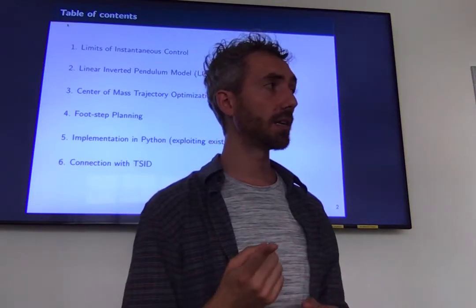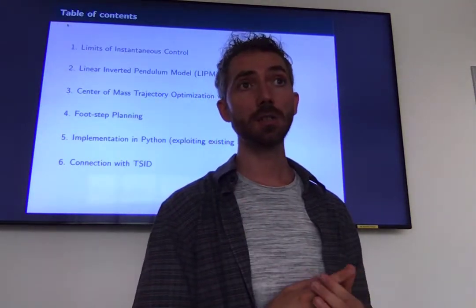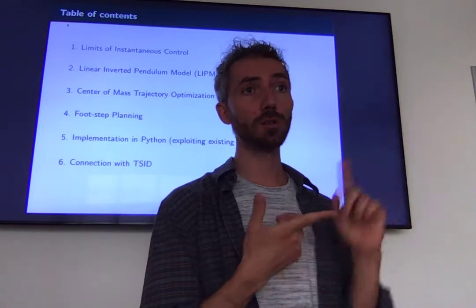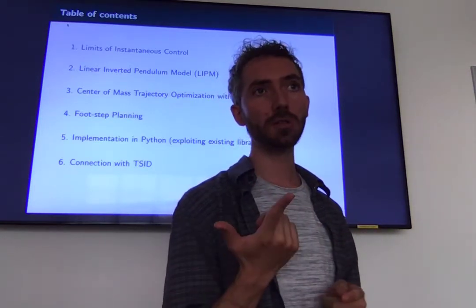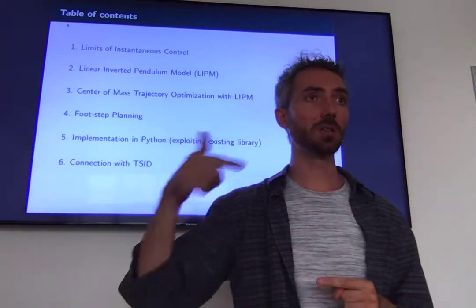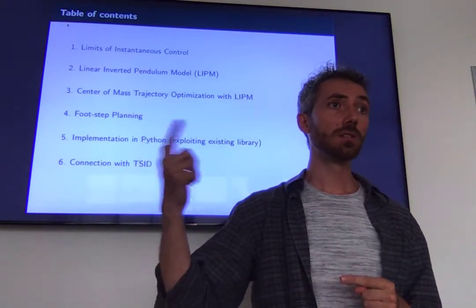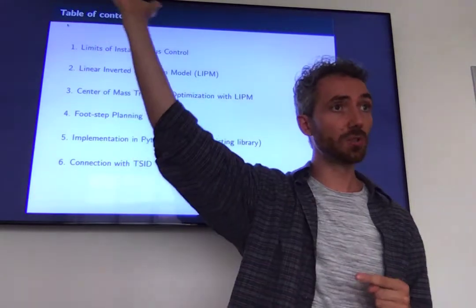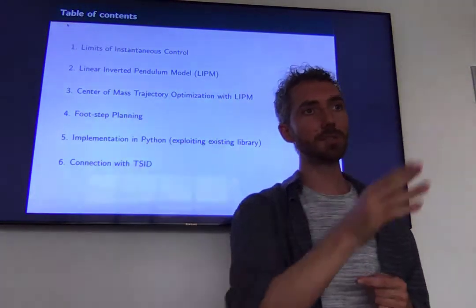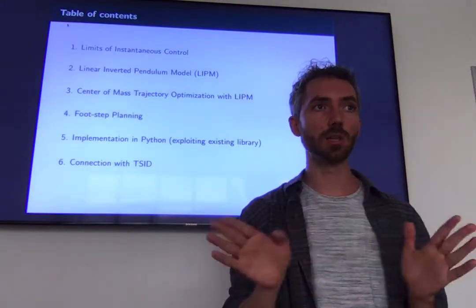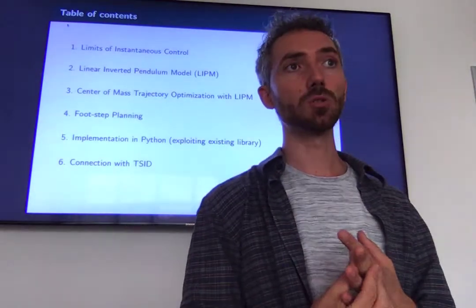There are other kinds of MPC, such as robust MPC or stochastic MPC, in which you really optimize for a control policy. Because when you start taking into account uncertainties, then you can no longer do an open loop integration. You need to have some kind of feedback. But in the classic MPC, you're correct. It's an open loop optimization problem.